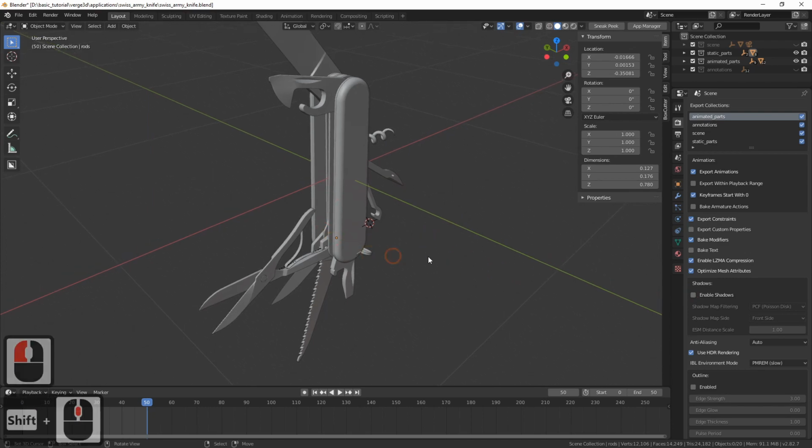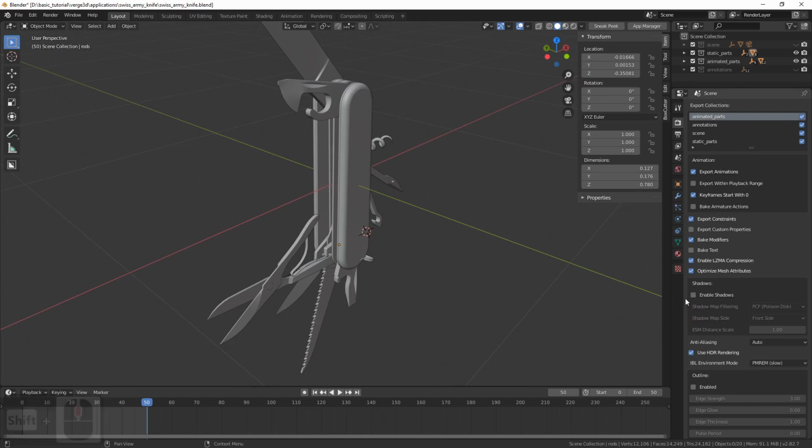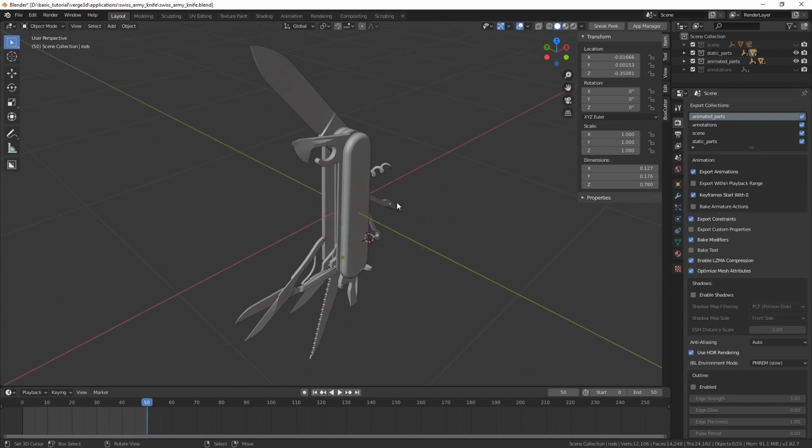There is one last thing we want to do. It won't affect this particular application because we don't use any lights. But just in case, let's disable shadows for this scene. Real-time shadows is a very heavy technique, so if you are not going to use them in your app, it is better to turn them off altogether to free the engine resources.